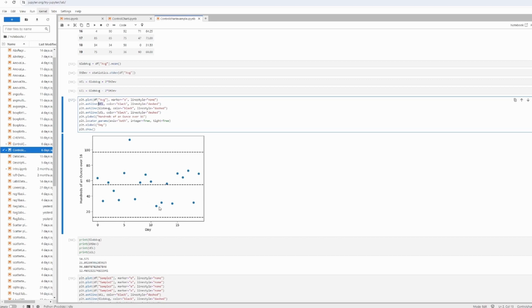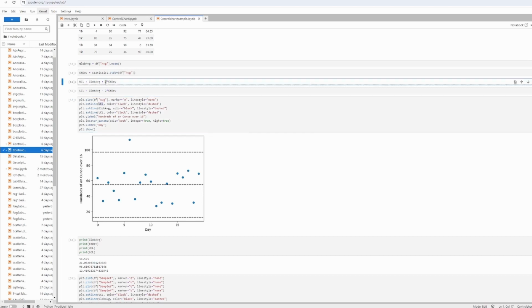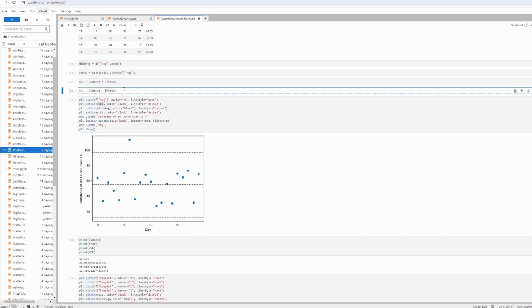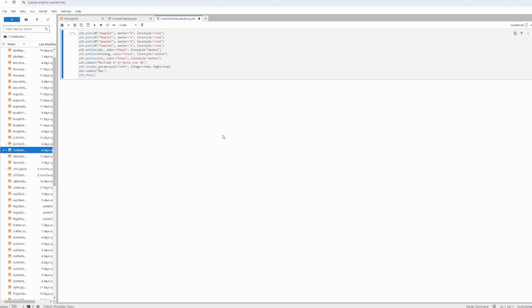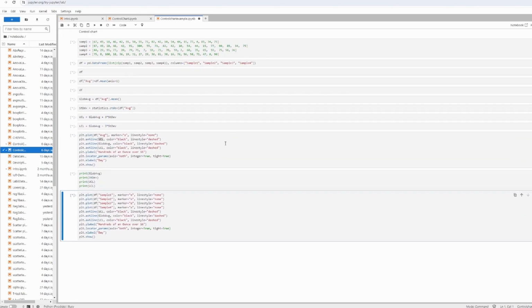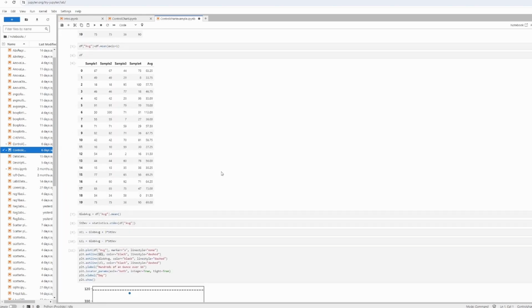And so we're going to see what's in spec. So these are all within specifications based off of 2 standard deviations. And this one here is outside of the spec. If we were to change this, we can see that our control chart might actually change. And what we can do here is try to run all the cells again and see if our control chart changes and if our value ends up within that.